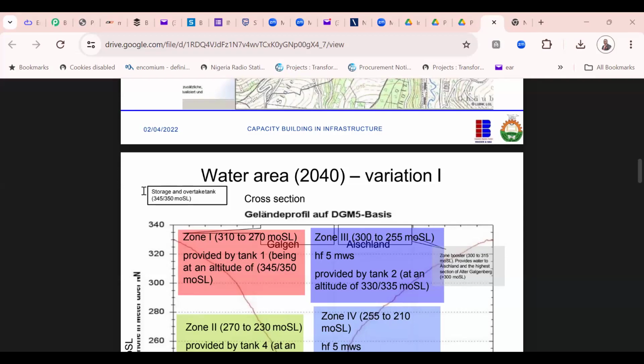So it means you have to have a reservoir, maybe at the ground floor, then build your own elevated tank. When you take water from the raw water tank, you can use your surface pump and push it up. Then from up, it comes down via gravity. That is why in building approval, they must know what you want to build and tell you whether it fits in.